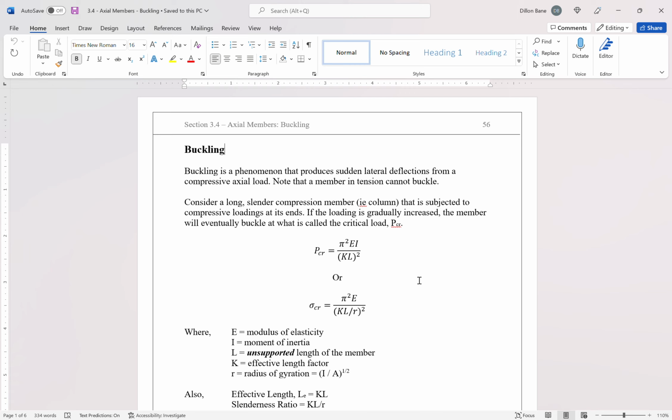putting that little piece of wire in compression. Okay, so if you can imagine that you've got this straightened out paper clip between your fingers, and you start pushing on it a little bit, putting it in compression, it will initially resist some load. You may be only pushing with a couple of pounds worth of force, but that paper clip is holding the load.